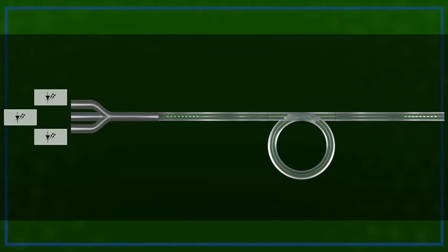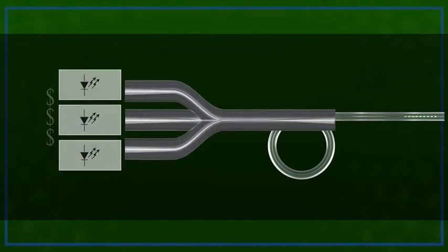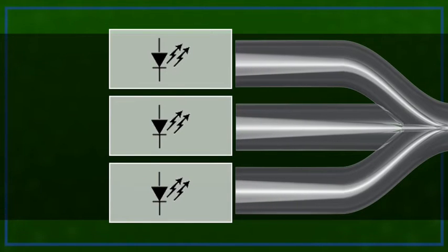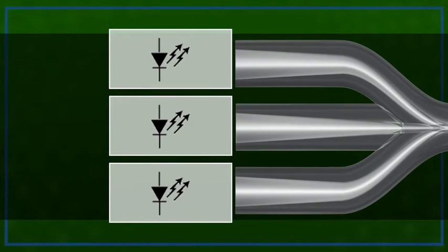Unfortunately, practical limits quickly set in when we try to add a third diode for a tripling effect, since each input would require a pump diode with a very small numerical aperture and ultra-high brightness. These diodes have a matching ultra-high price, not practical at all. More economical high-power pump diodes have a larger numerical aperture and a larger diameter output fiber.